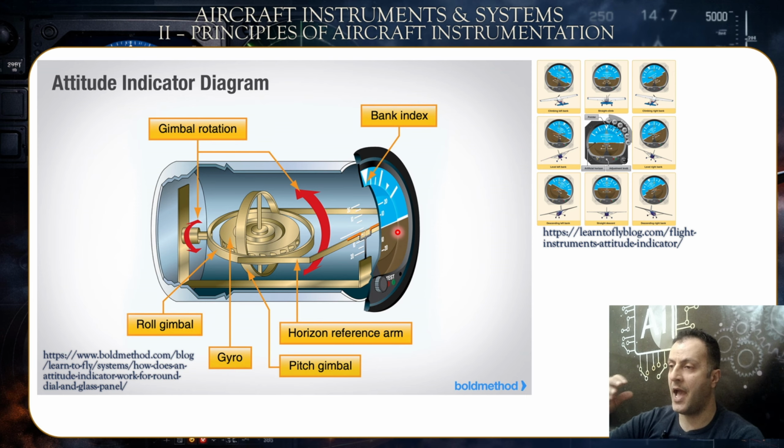But you would have this sky, okay? So it will show you this horizontal line, which is the reference plane of the aircraft, going up to the blue area of the blue and brown disc, which would indicate to the pilot that the airplane is pitching up.